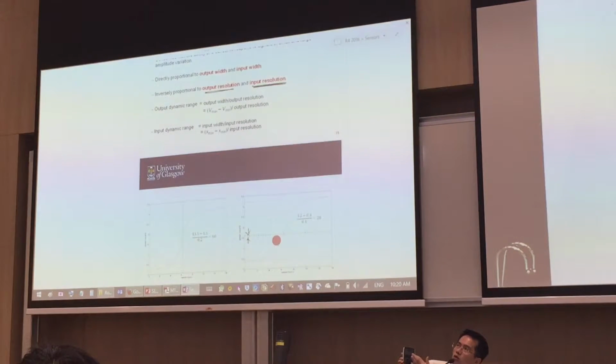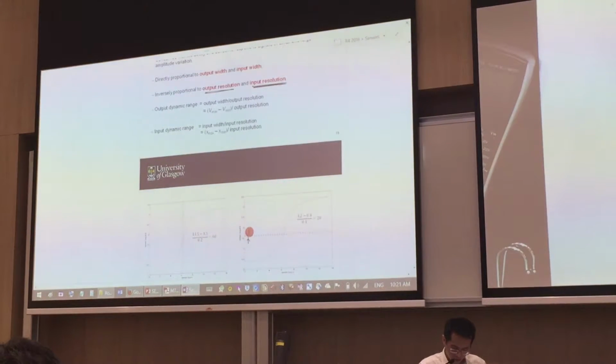For anything that's 0.01, it couldn't differentiate. 0.02, it couldn't differentiate. Because its resolution is up to 0.1. That means if there's a change of 0.1, this thing can sense it. So its resolution value is that. So in this case, this sensor over here is quite small, but the value is about 0.1 for the output. This is what we call the output resolution.